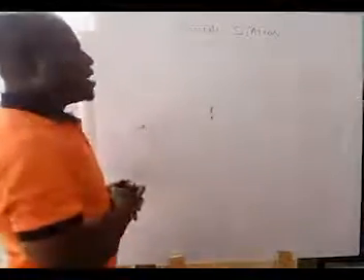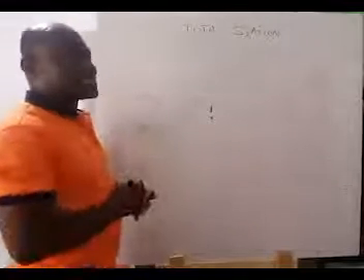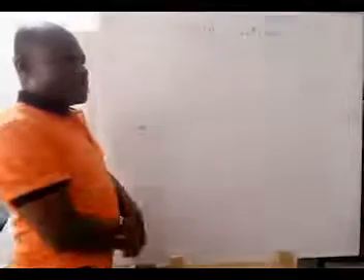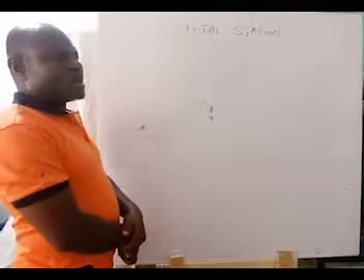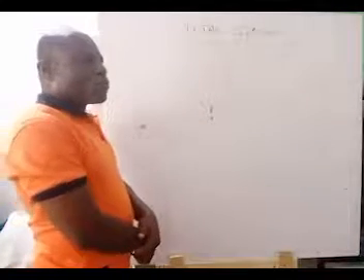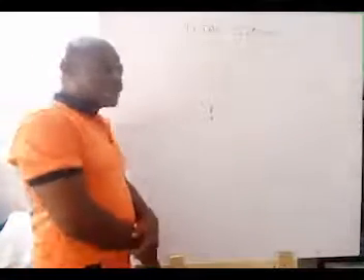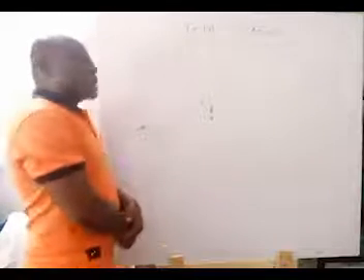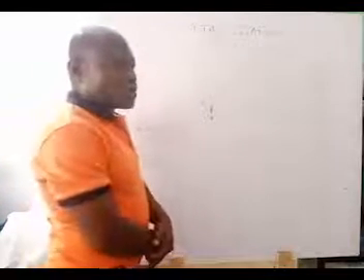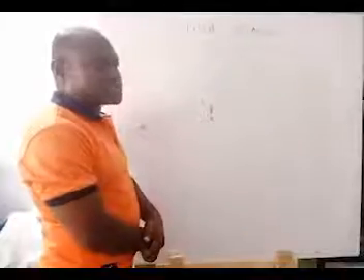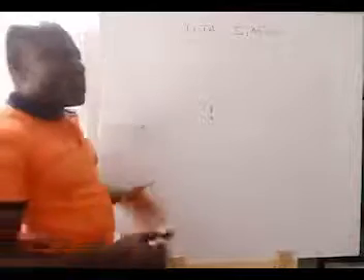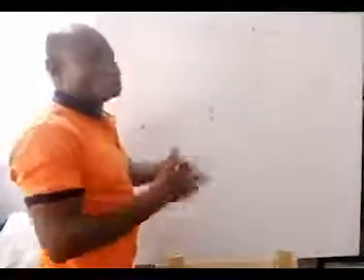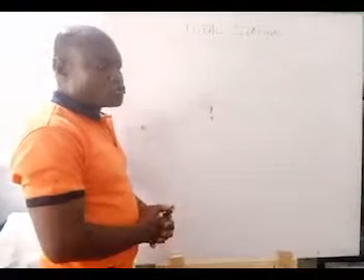Now, you can use the total station to do an as-built of the construction stage, where we want to find out some of the things that might have gone wrong or any change that must be done. You can use it to do what we call an as-built. Pick points, plot them in AutoCAD Civil 3D, and then you check out any disparity. Then you make decisions on changes or what you do going forward with the construction.